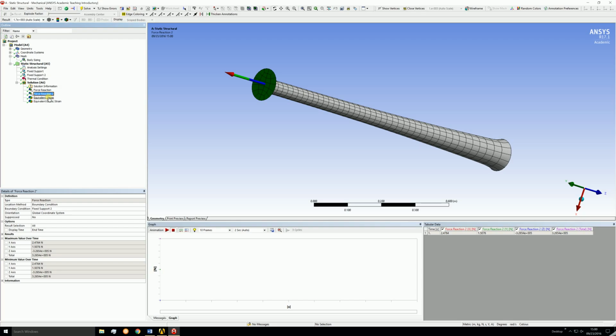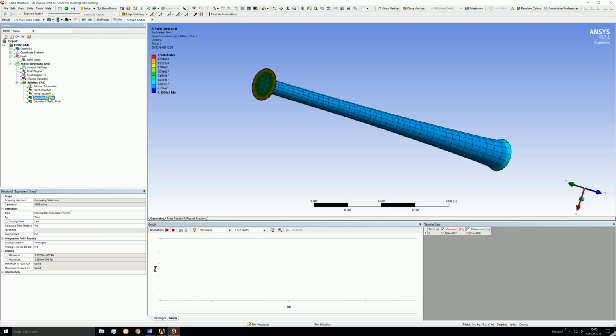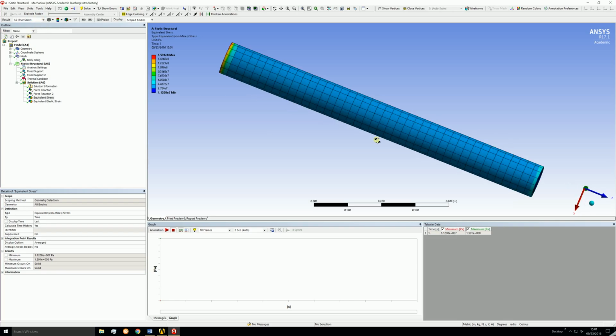Now, upon selecting the stress or strain results, you should see the bar highlighted in different colors corresponding to a scale of stress or strain. Now, you should notice how this bar looks a little deformed. That's putting it mildly. But that's just because of the scale. You can select 1.0 for true scale. That's what the bar would actually look like were we to run this in real life. Well, you can't really run it in real life. Well, run the experiment, I guess.